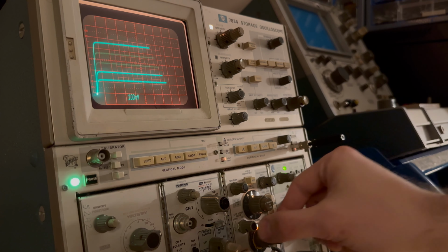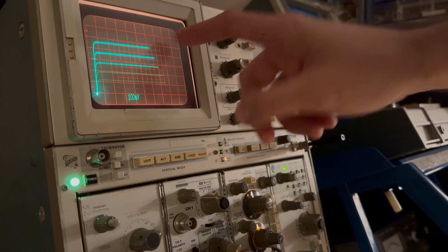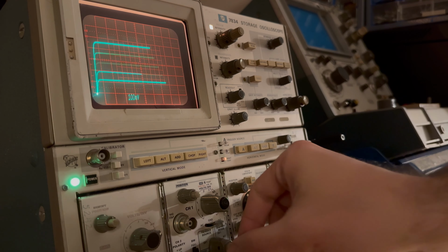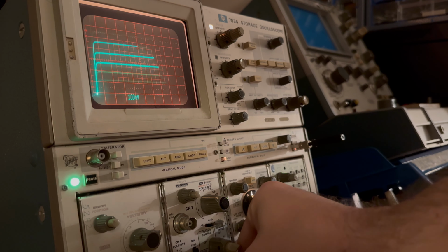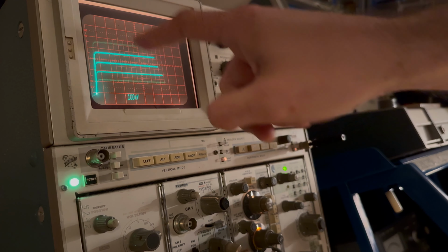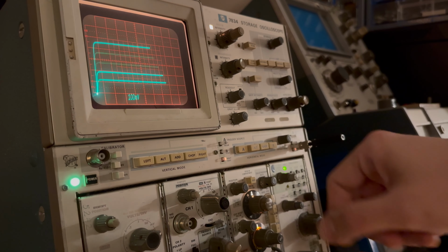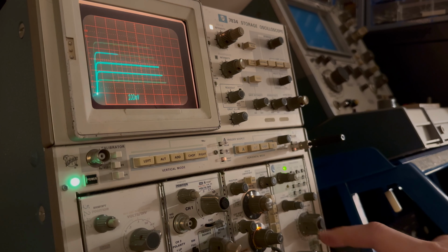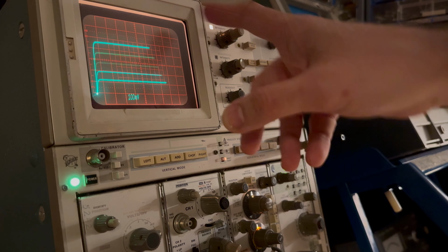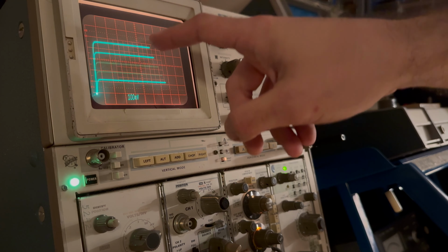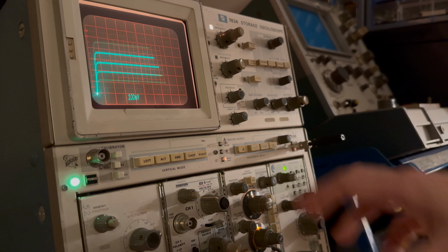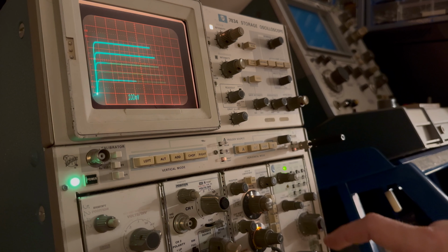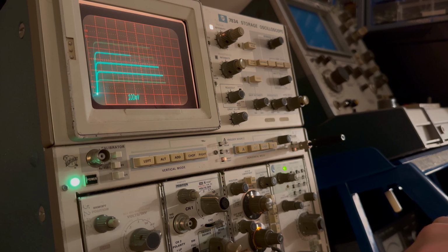You can see there's no artifacts on the display when switching between the characteristic curves. That's very important. And you can also do some basic math on this, so like figure out the gain of the transistor, knowing the current per division, vertical, and the step amplitude, and stuff like that.